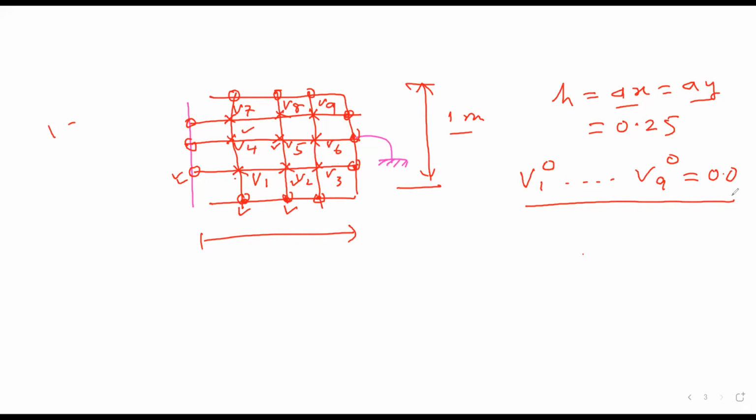So with this, let us start with calculating V1. Your V1 would be equal to what in your first iteration? It would be equal to 1 divided by 4, potential 0 plus 100 volt. No other potential is there in V4, and the potential for your V2 is also assumed at 0. That will be equal to what? Do you have a calculator with you? Try to calculate it.